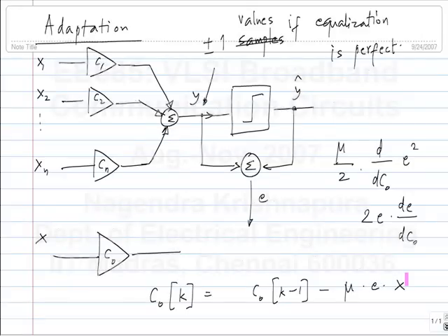It's also important, as we saw from the curve, that if you update the coefficient by a large amount, it can go in the other direction, meaning the error can be large but in the other direction. So at that point it won't converge. It will keep swinging between points of large error. So the mu has to be small enough. We'll see exactly how it is related to the filter. Mu has to be small enough in order to give you convergence of E to a minimum.